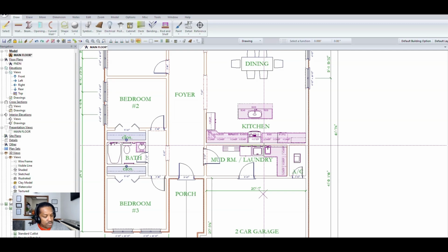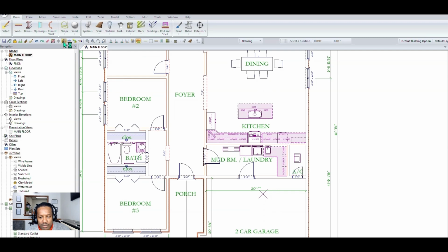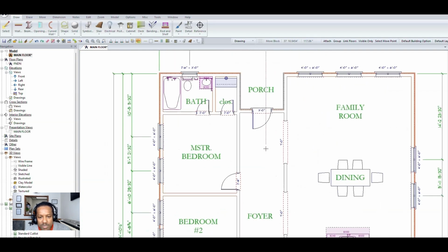Alrighty. So now that we have that CAD file imported and loaded into the software, let's go around and check. And again, if any walls come through with improper thicknesses, go ahead and correct those walls and make sure they have the correct thickness. I just noticed that our floor drain is in the wrong place, so I'll move that over. If you import things in, things sometimes need to be adjusted.